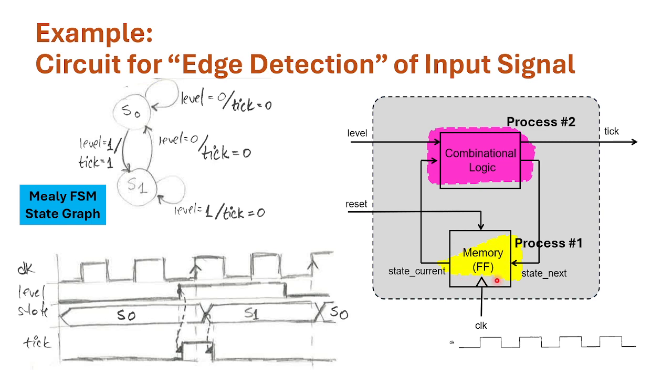The operation of this is to simply imagine behind these flip-flops D-type flip-flops that will latch, take what we have at the input and copy to the output and keep it so for the duration of a clock period. Assuming that this operates on the rising edge of the clock signal, what we have at the input as state next is taken and latched at the output.